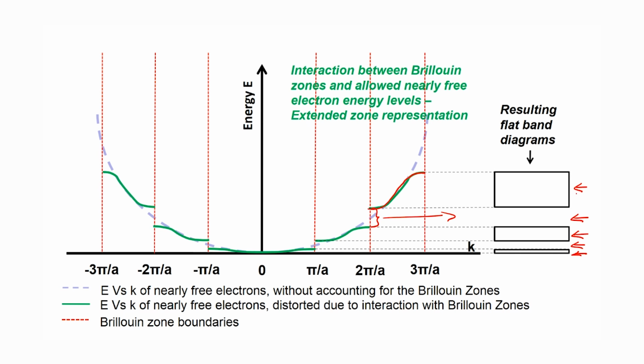If these two were the last two bands that were present in the material, then yes, we would call the topmost band the conduction band, and the immediately lower band which is full would then be referred to as the valence band. So, this is the way in which the material begins to show itself, and the one additional detail that we need to add here which will complete the picture is the presence of the Fermi energy, which is the highest energy level occupied by electrons.